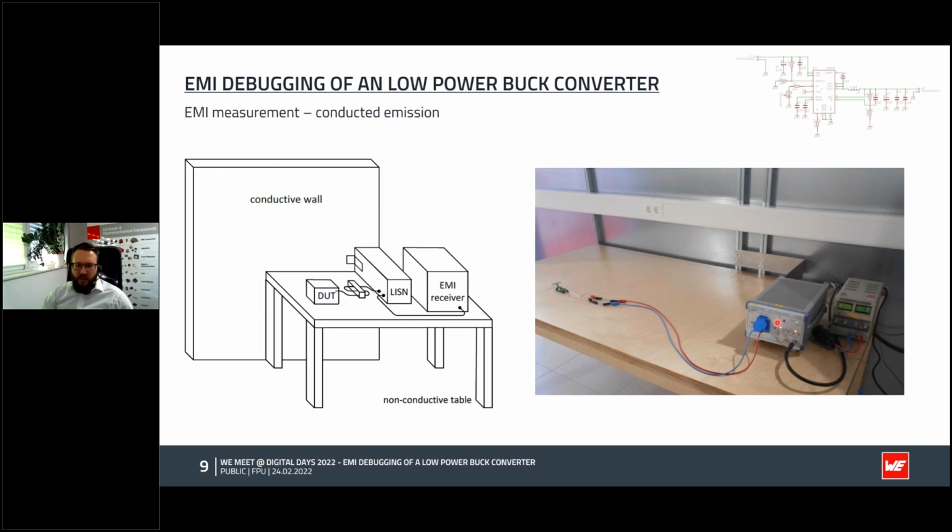The voltage supply goes through our LISN, a two-line V-LISN. We measured according to CISPR 32. And this was the cable. We have quite long cables here, and what is also really important is the placement of the cable. It depends on how big the distance between the cables is and so on. It all changes or influences the measurement. And we have some static load here.